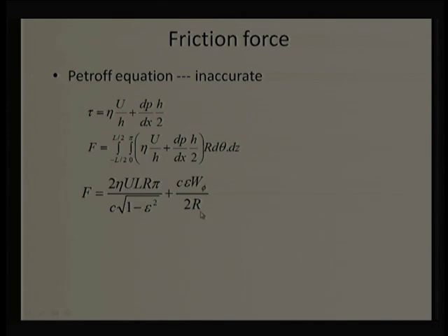And we try to see this friction force relation, W sin phi, which can be given in terms of other parameters like eta, u, L cube, c square, and we see a number of terms are common in these two. To simplify, we can take some common terms and compare the first term with the second term. If the second term is negligible, for our simple calculation we can neglect it, but if it is not negligible, then we need to account for a slightly more complex problem.